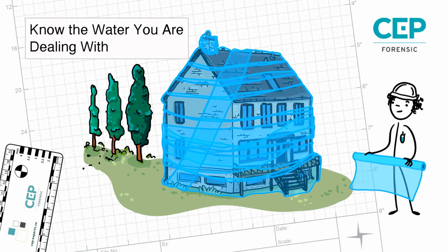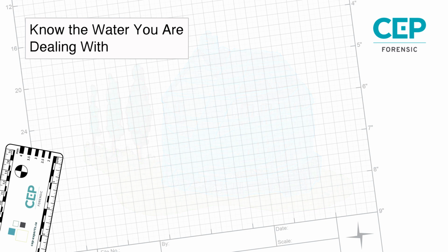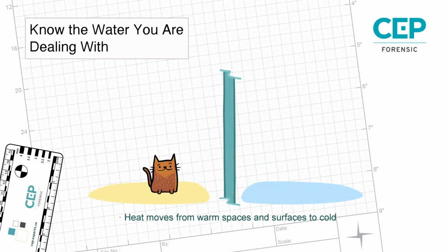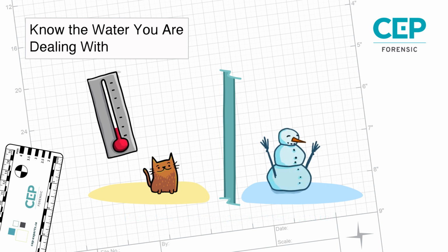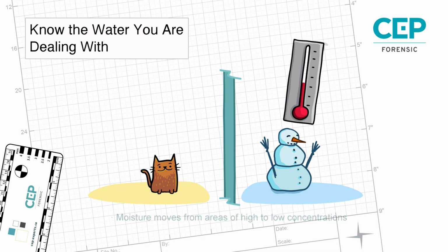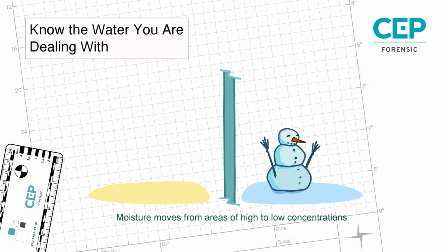In the presence of a design flaw or construction defect in a tighter building, moisture that finds its way into an assembly through air leakage may not have the ability to dry out. Air leakage and vapor diffusion commonly occur when temperature gradients across the roof and wall assemblies are high. For example, in winter when a building is heated and summer when a building is air-conditioned.